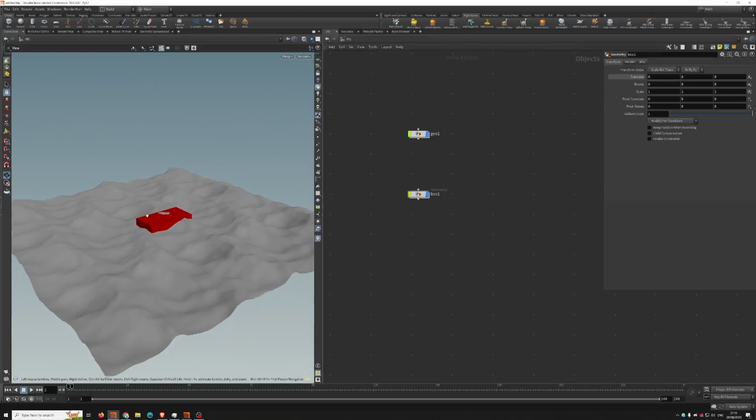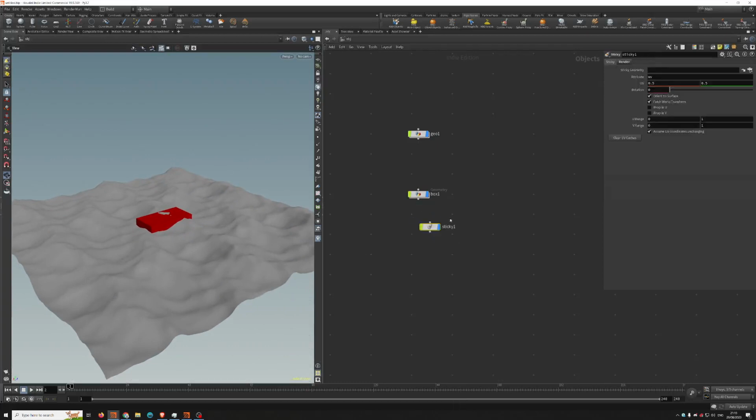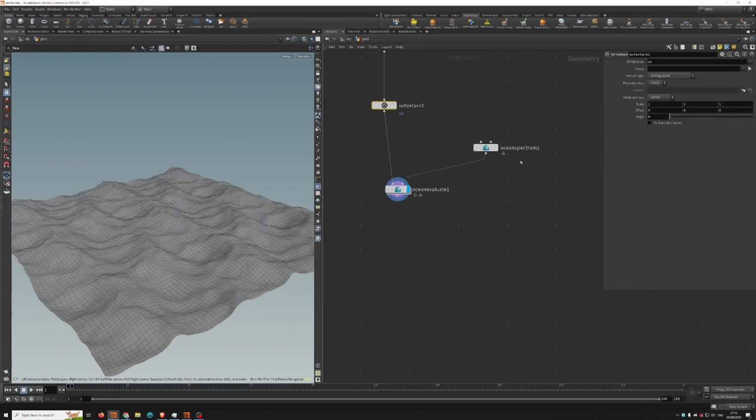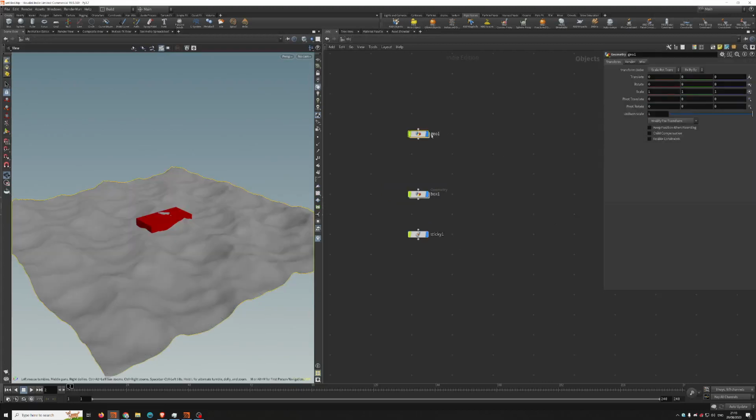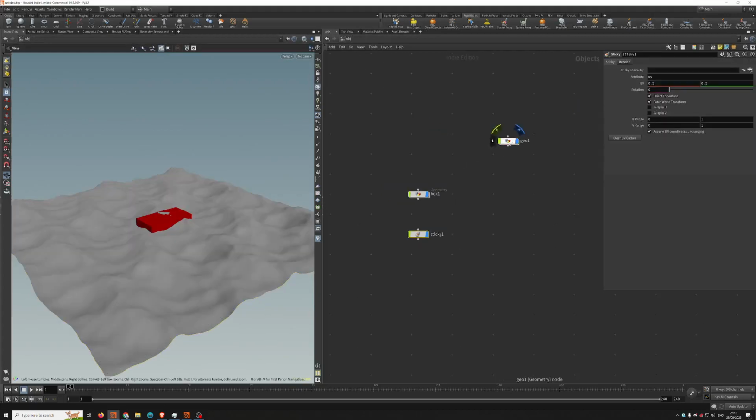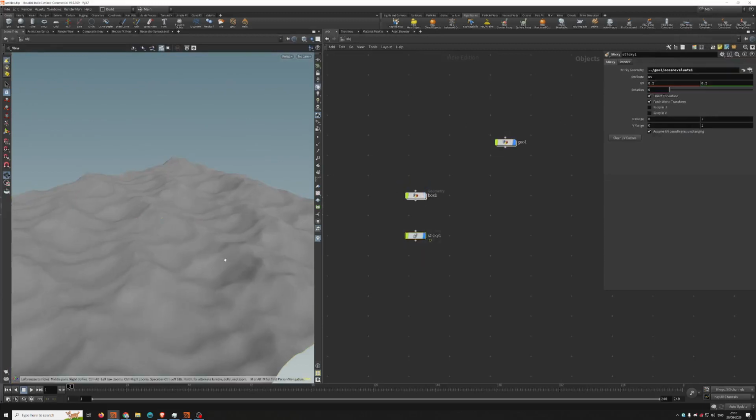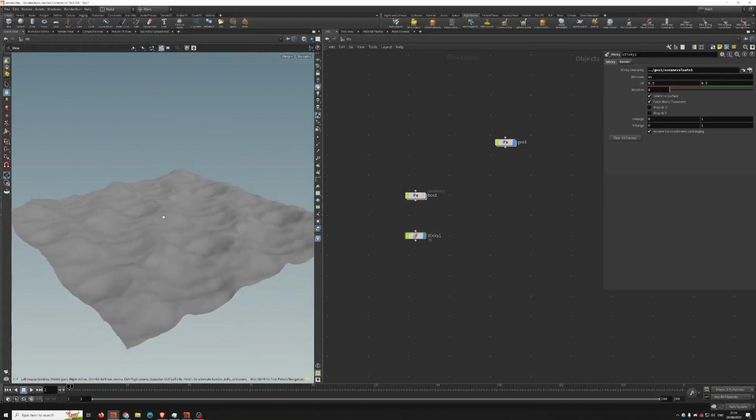All right, first thing you do is you bring something called sticky in Houdini. When you type sticky, you get something like this, and in this sticky, we want to get the ocean evaluate in the stick geometry. So I mean where I have to stick it. So I just want to go to the ocean evaluate, and let me put it inside, but I just want the ocean evaluate. But let me show you what is going on.